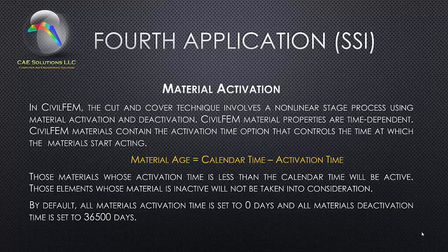CivilFEM materials contain the activation time that controls the time at which the materials start acting. The material age equals the calendar time minus activation time. Those materials whose activation time is less than the calendar time will be active.